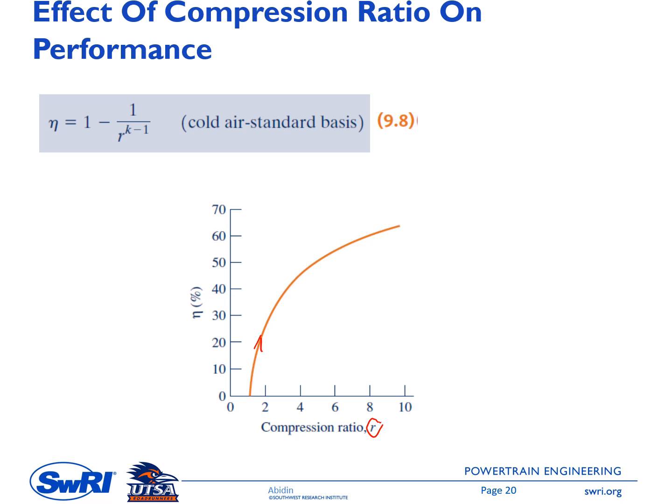And again, this is the reason why in engine design we try to maximize the compression ratio as much as possible, and for sure there is some limitation there. For example, in a gasoline internal combustion engine, it is limited by knocking, and in diesel combustion we do not have knocking, but it is limited by the material strength. Having a higher compression ratio means also higher compression pressure, and thus also higher combustion pressure.